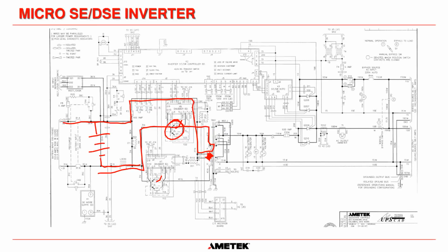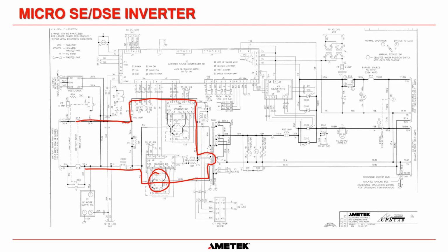Once again, that gives us the square wave going that way. And then if we switch Q2 and Q4 on, it will go down through this transformer, out through that way there. That gives us our positive half. And then the result out of the system here is our sine wave. Okay. That is the ferroresonant transformer there, and we get a sine wave out. And that is a constant voltage sine wave.